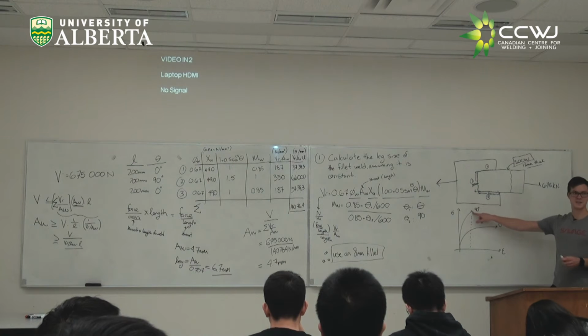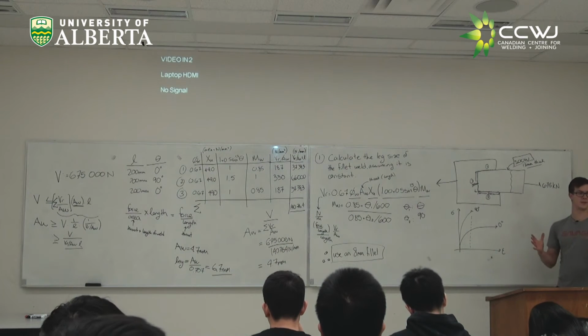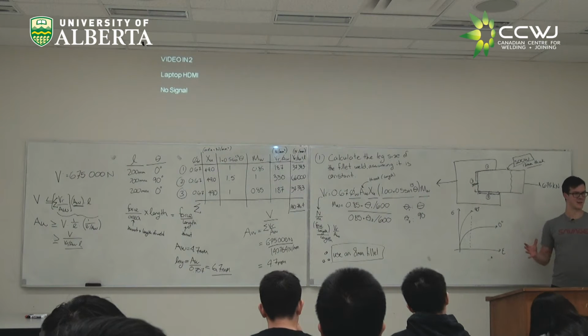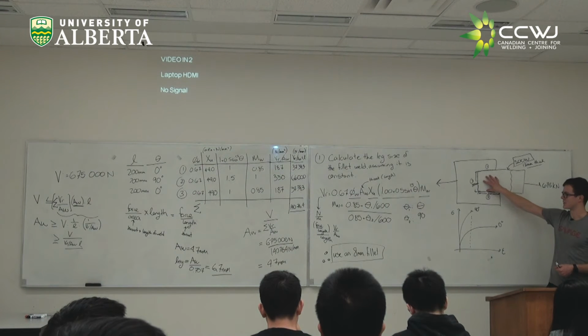Now, when our weld is at this failure point, the rest of our welds, we're going to assume are all acting as a unit with this weld. So the strain in our welds has to be all the same. There's a little bit of an approximation here, but you can imagine that this is a fairly rigid plate. You can't have completely different strain here as you do over here, right?